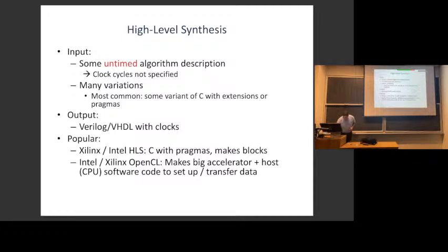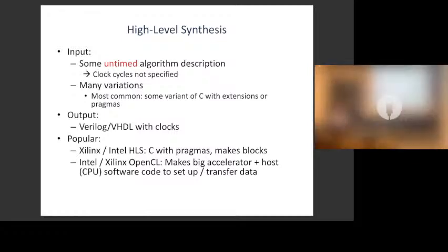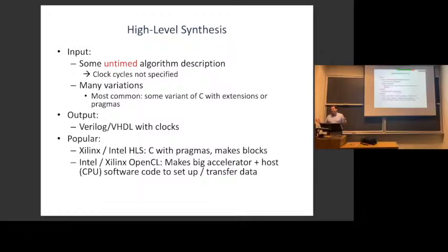And there's a lot of cleverness that goes into this. So popular versions of this, both Xilinx and Intel have high-level synthesis tools. So it's basically C with these pragmas. And what those ones are targeted at is basically making blocks. So they don't try to make an entire design, but you might have, for example, a finite impulse response filter, or maybe that quadratic equation that I showed as an example. You might be just trying to take that much code and make it into hardware. So you're not trying to describe your whole system. Usually it's like some hardware block of kind of moderate size. And then you're going to hook that up to the rest of your hardware.